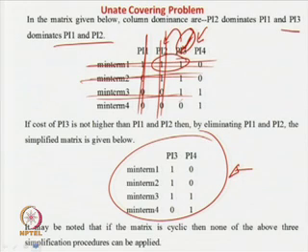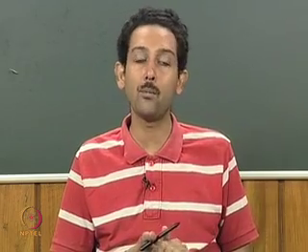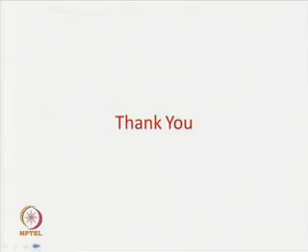So, in other words, the row dominance and column dominance definitions are the same, but in row dominance you keep the row which is dominated, that is, the one with fewer ones, and in column dominance you do the other: you keep the column which has more ones, that is dominating. In a column we require more ones, because a column with more ones means more capability of covering the rows in a single prime implicant. So, that is the idea. With this we come to the end of this lecture.